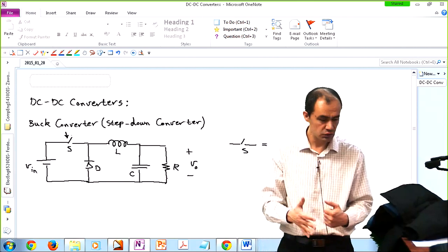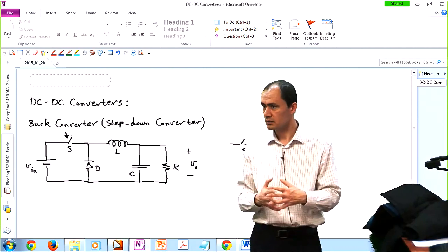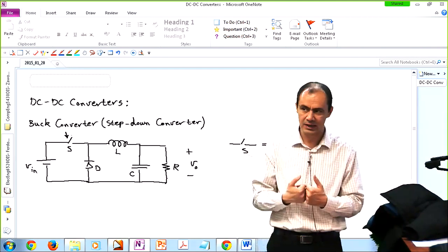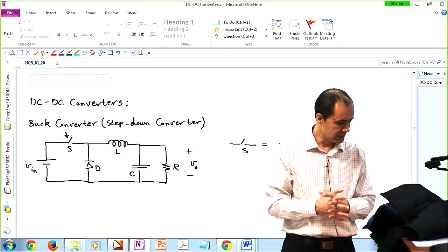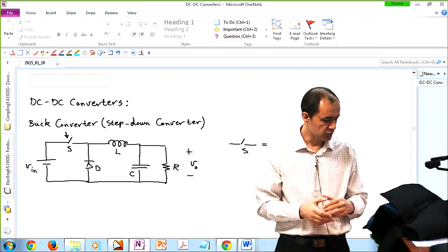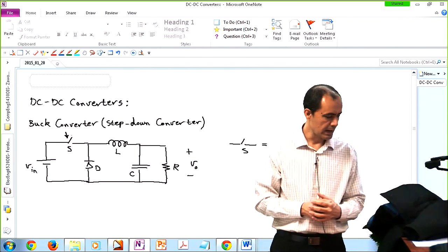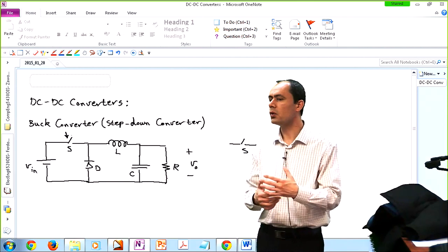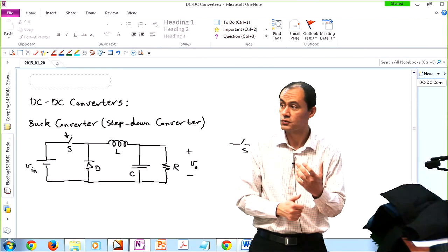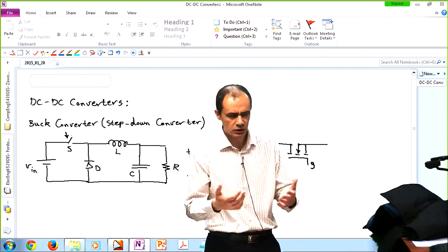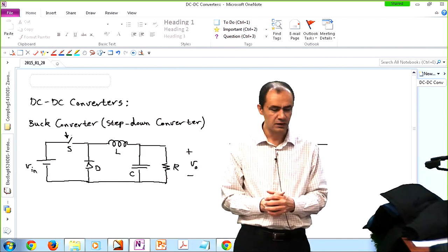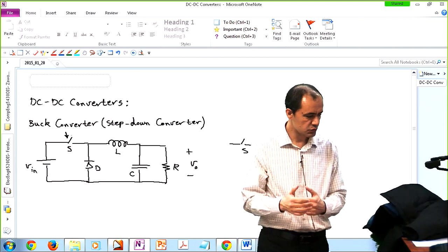All right. In power electronics, we usually assume that the elements are ideal, in a sense that if I have a switch and this switch is closed, it is like a short circuit. There is no voltage drop across this switch, so it's an ideal switch. Obviously, in practice we don't have ideal switches, but it makes a lot of sense to assume our switches are ideal because, for instance, if your input voltage is 100 volts, and in a real switch you have about 1 volt of voltage drop, that is compared to your input voltage of 100 only 1%. So it's a good approximation to assume that this switch does not exhibit any voltage across its terminals.